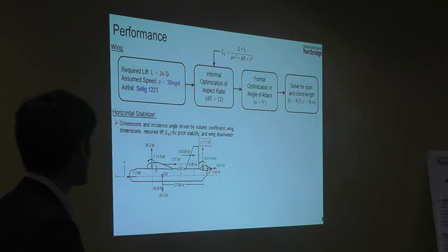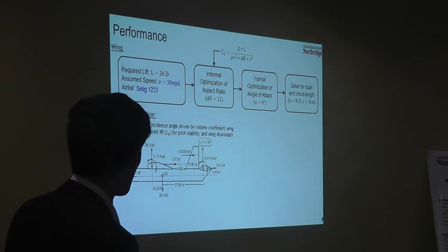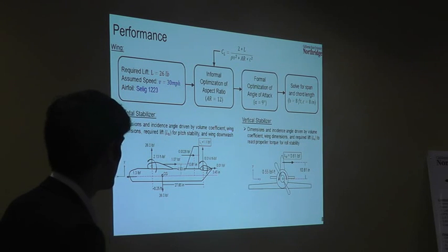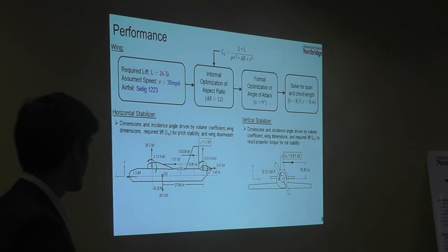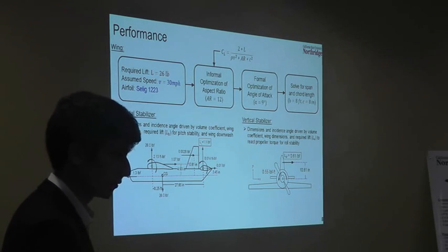The horizontal stabilizer, meant to react the pitch and lift from the wing, was offset by the wing downwash and also other wing dimensions, and was based off of the horizontal stabilizer volume coefficient and controls the pitch stability. The vertical stabilizer had a similar procedure, and you can see in the free body diagram that it was designed to react against the propeller torque for roll stability.